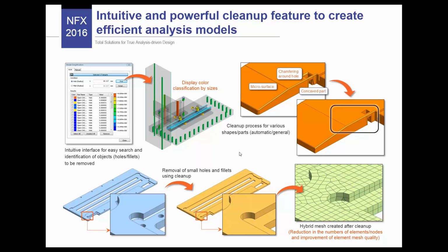So midas NFX provides such features of defeaturing directly inside the interface. You have automatic defeaturing, so you can directly get the holes and the fillets and remove them, and you also have manual types of defeaturing. A lot of people are telling us it's quite similar to SpaceClaim, some of the features to remove edges.